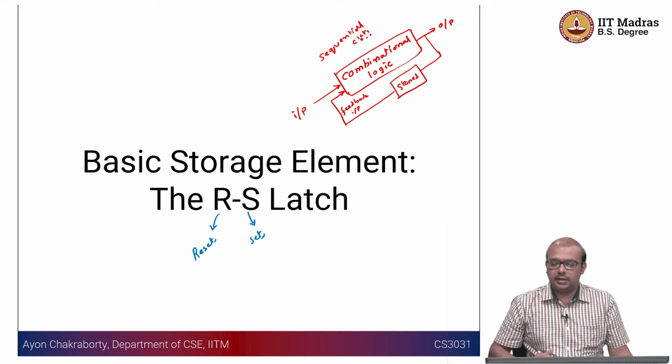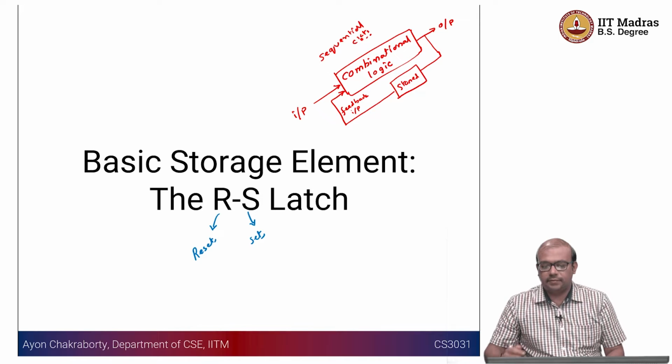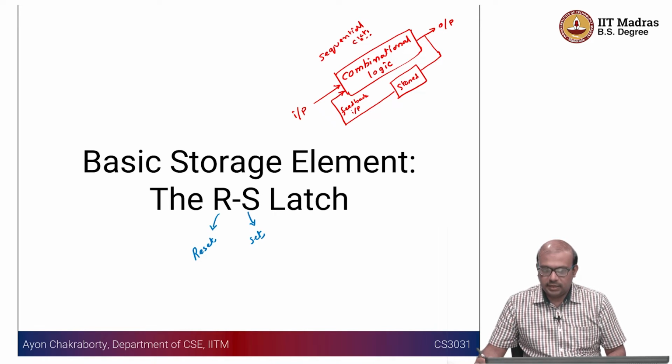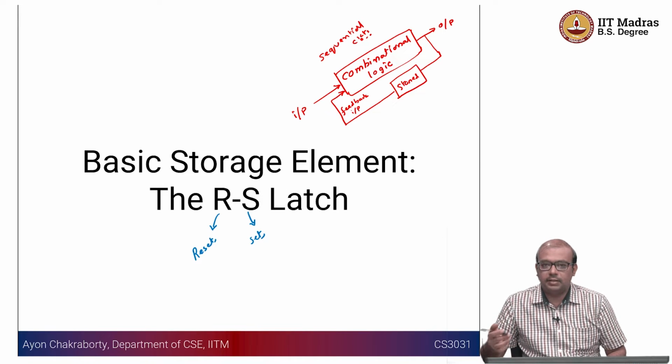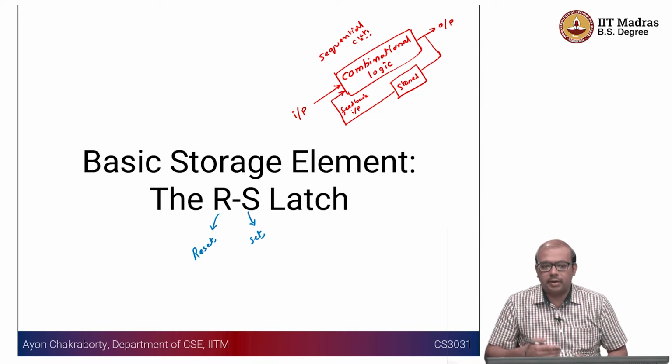The reason there is a temporal dependency is why it is often called sequential. Whatever is the output at the current stage is going to influence the output for the next stage, or next state. So we gave you an example in the last class, which was a counter. Briefly recalling, a counter is a device or circuit which counts from a number in a monotonically increasing order to another number and then wraps around.